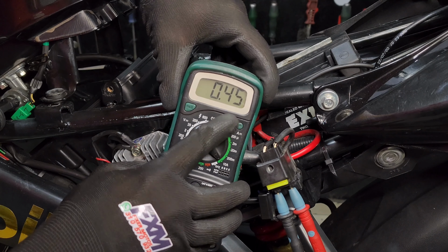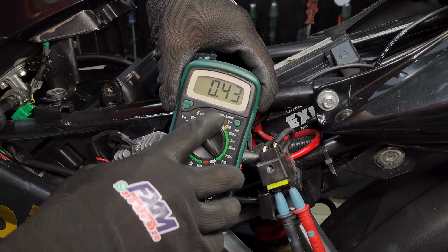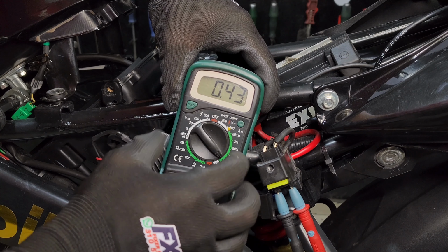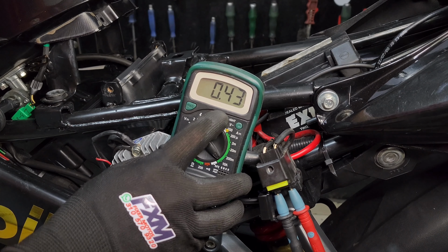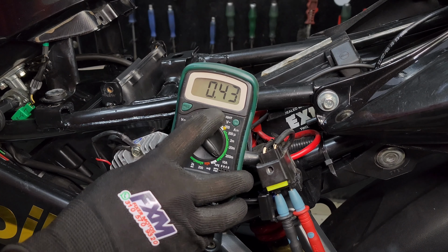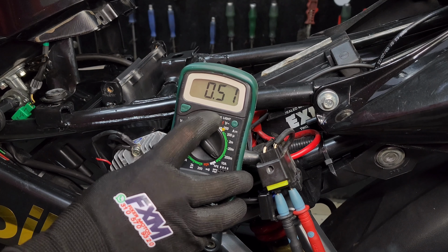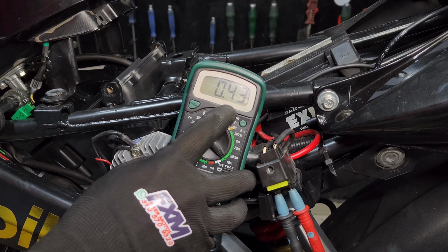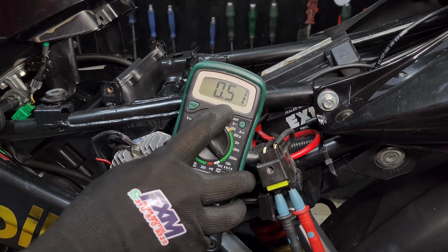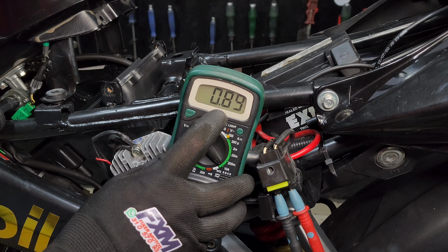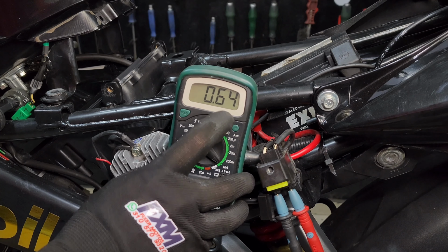And here it already shows us some initial consumptions. What are these initial consumptions? From the instrument panel, from the witness light that is turning on. When I activate the brake, there we see that the amperage increased because the consumption has increased. When I activate the left signal, we see that there is a consumption and it is also intermittent. What is intermittent? Well, because it is working with the flasher.